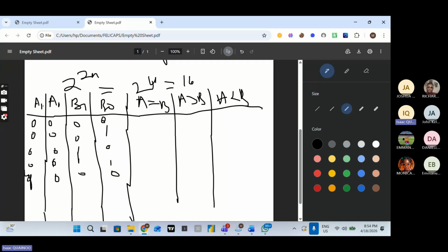Once you break the pattern, if you are to minimize using a K-map, your answer will be very wrong. Because you are going to label the min terms, M0, M1, M2, M3, M4, etc., and that's what you are going to use for your K-map, which is going to be very wrong.